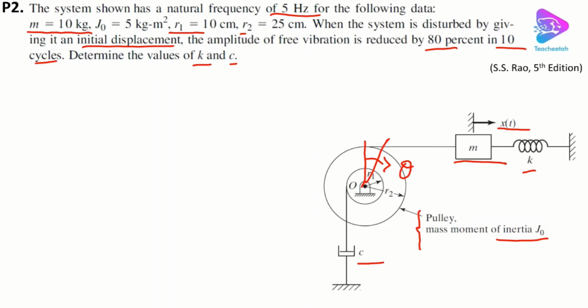If we suppose that we have a small amplitude of vibration, so theta is small or x is small, because it's a vibrating system, we can suppose that theta is a small value, say for example less than 6 degrees, and then sine of theta equals tan of theta equals theta. We had these assumptions before.